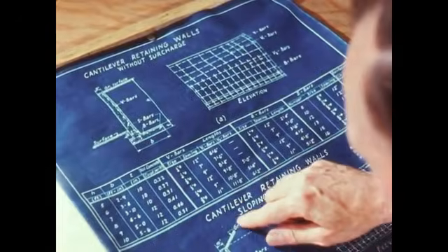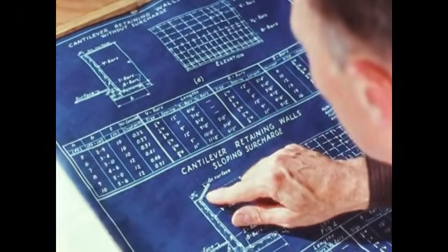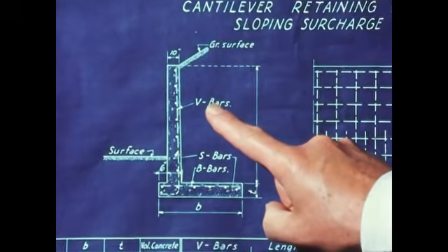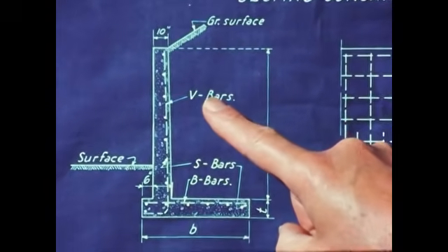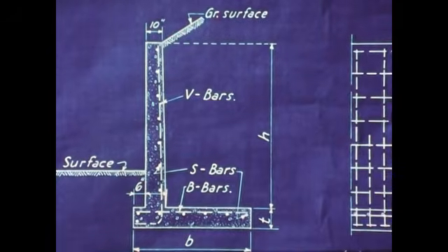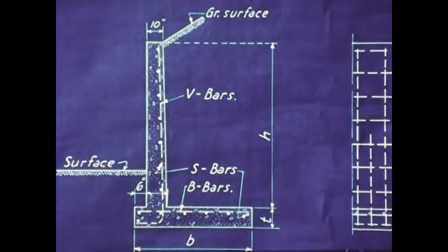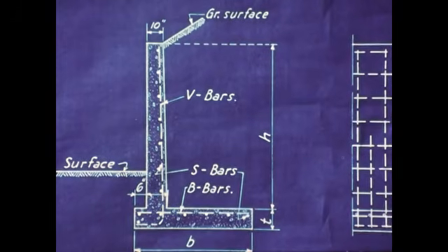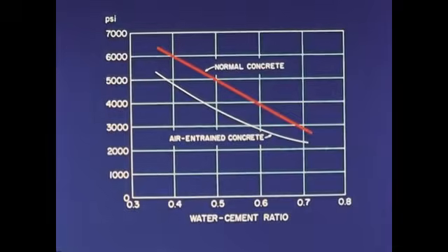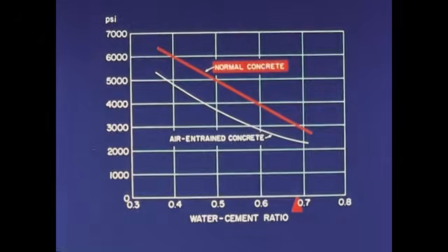Problem: design a mix for a 10-inch thick concrete retaining wall to be built in northern Wisconsin, a region of widely varying temperatures. The wall, which will carry no vertical load or impact, can safely be designed for 3,000 pounds per square inch. The 28-day water-cement ratio strength table for normal concrete shows that 0.68 pounds of water per pound of cement will produce this concrete.